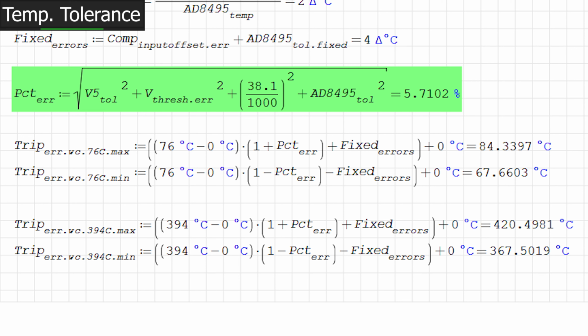For reference, a mechanical thermal cutout, which relies on a material melting, is rated for an absolute tolerance of 5 degrees Celsius. I mean, we're in the ballpark, though to be fair, that is a non-resettable TCO and a fixed threshold, so they can make some design decisions because they don't need the flexibility. This design has a tolerance of 17 degrees, so 3 times more variance in the trip temperature, but this is a resettable and selectable threshold system.